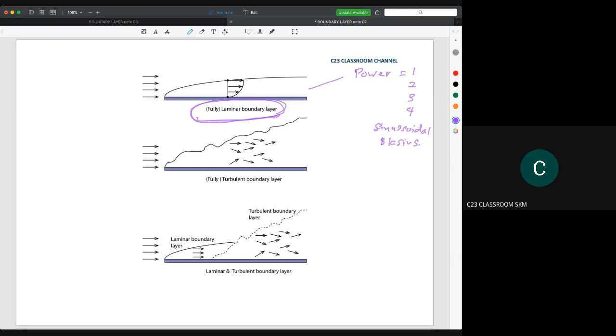At the least, you could use all these velocity profiles to calculate delta star over delta and theta over delta, and then you could use the idea of von Karman to derive the equation for delta, the equation of C small d, meaning the local drag coefficient, and also the total drag coefficient.